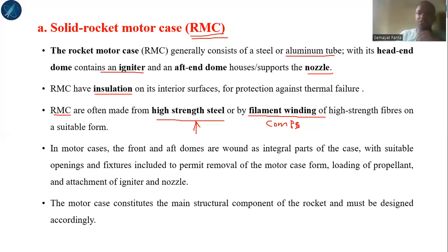They combine together to form a material with better performance. For example, if you use some carbon material with epoxy together, epoxy is very weak in property, like in tensile strength, and carbon is weak in compressive strength, meaning when we compress carbon, it can easily break. When these two come together and are combined in some pre-designed method, we can get a very high strength material that is called a composite. Filament winding is one of the techniques of manufacturing composite material, among others. There are casting methods, and there are also many other methods.